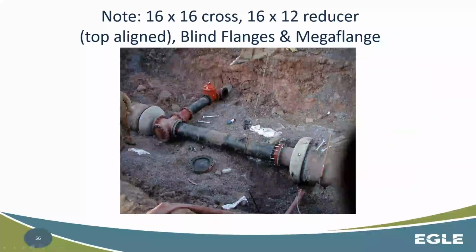So you have a couple of blind flanges here. That's these rounded domed cap things that are basically reducing this 36-inch concrete main that's over here and over here. And notice that they're actually rounded. That's basically just to prevent direct stress in a certain way. It's minimizing that. So it kind of flows down in and reduces into this 16-inch. So you have a mega flange here. That's really holding it together with a bunch of bolts here.